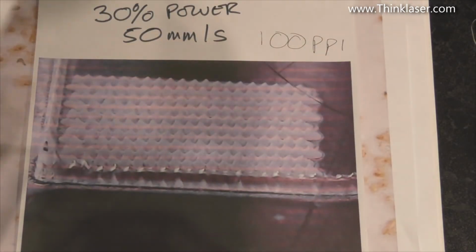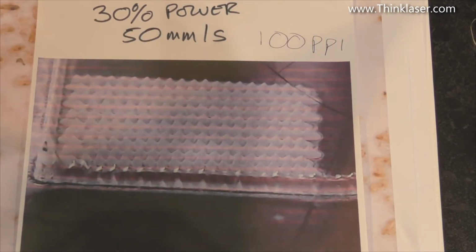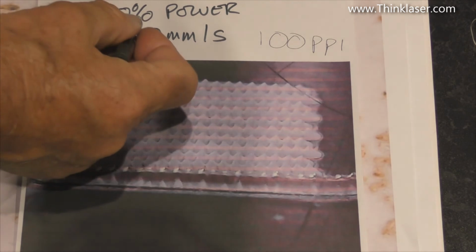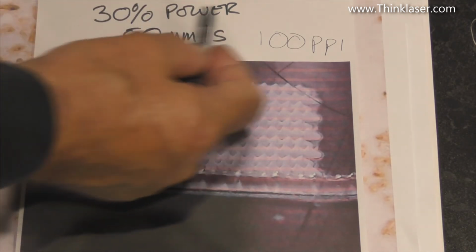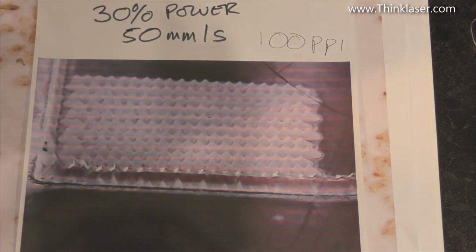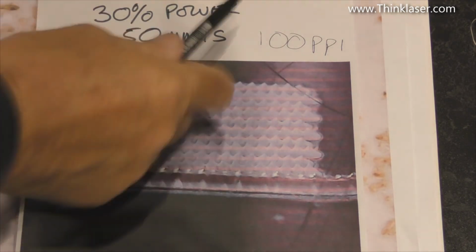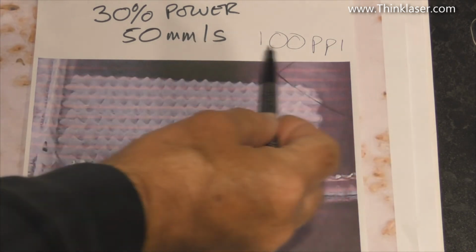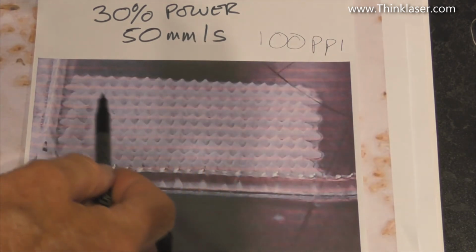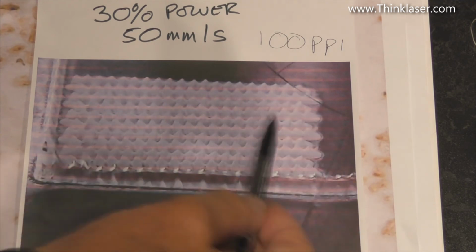Now, just coming back to this, this was done at 50 millimeters a second, very slowly, but it's done with 30% power, 35 or 40 watts of power coming out of the tube. And this is a resolution of 100 pixels per inch. That's what this picture was done at.